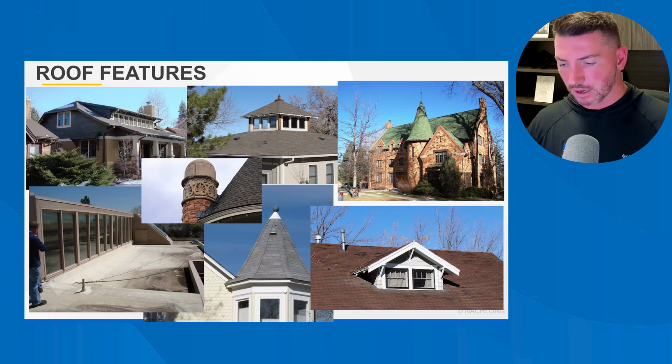So installing conical roofs requires special roofing techniques to get shingles to lie flat, especially near the peak. Inspecting these steep roofs closely is difficult or impossible without special equipment. That's one of the primary uses of a drone, is to inspect areas like that. So you can get as close as you can using binoculars or to look for signs of leakage beneath these roofs. The good news is, because they're so steep, they don't often build up a lot of ice and snow, so they'll shed pretty well, but the installation issues can abound because of how difficult it is to roof those.